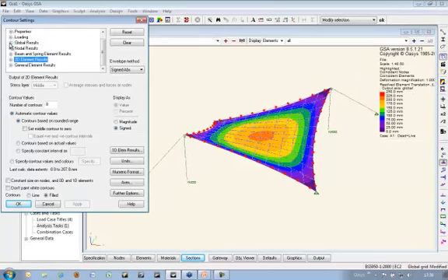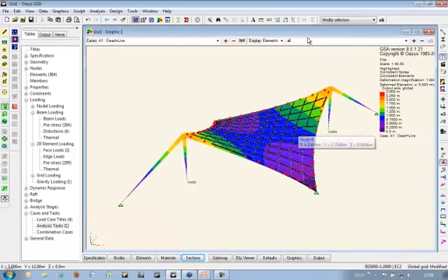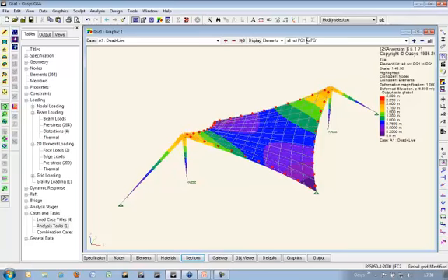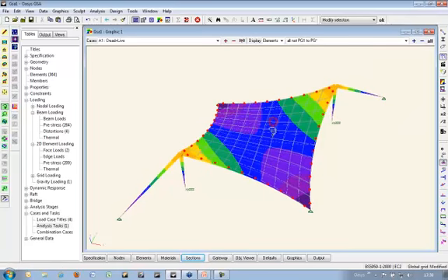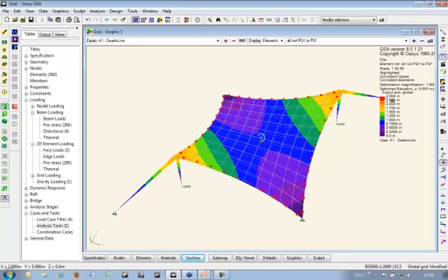Now, if you're worried about ponding on the structure, I can look at the global results, the deformed elevation. Or let me switch off the spaces. If you worry about the risk of ponding, if there was ponding occurring, you would get sort of an island of contour in here in the middle, and you then got ponding to deal with.